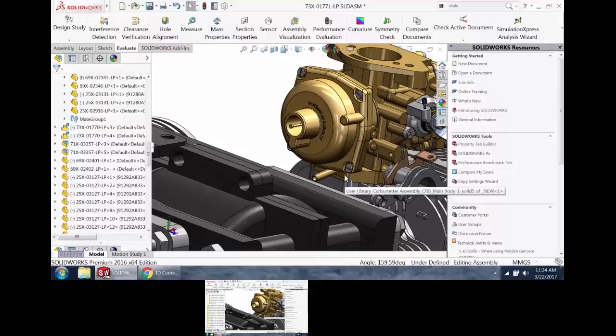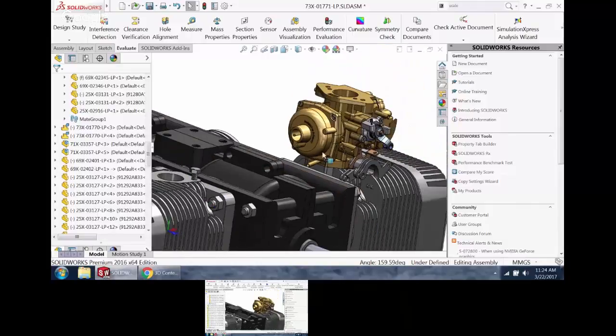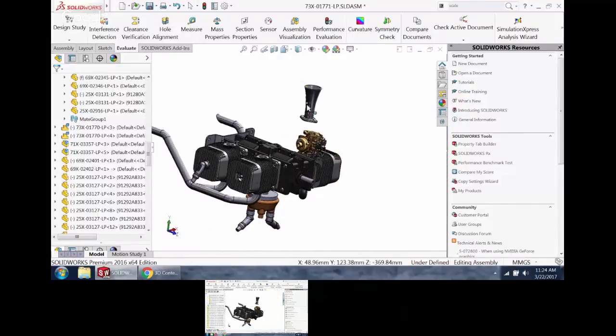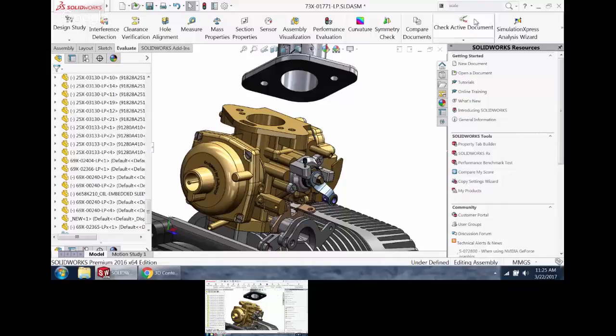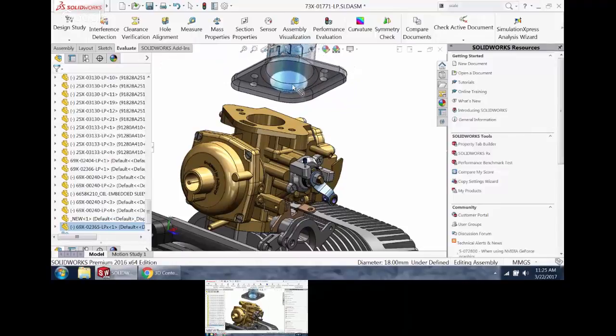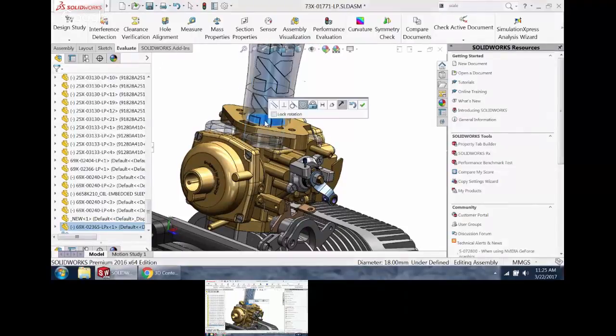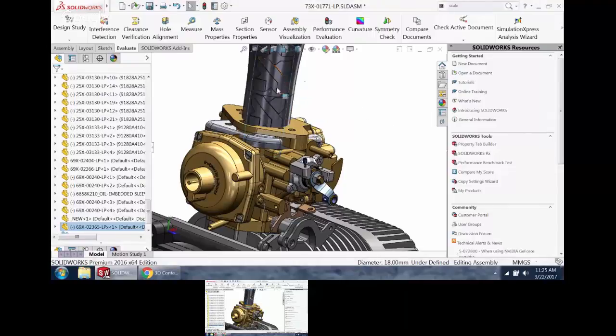Cylinder to cylinder is concentric, but you saw on that pop-up, you can switch up and pick any mate between those two faces. If you just hit the check mark, it'll pick the most obvious one, but if you override it, it'll change that for you. So cylinder to cylinder makes a concentric. You can hold the Alt key down, pick a cylinder. When it comes over another cylinder, it puts that mate on there.